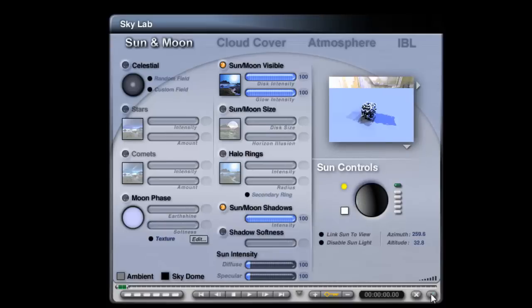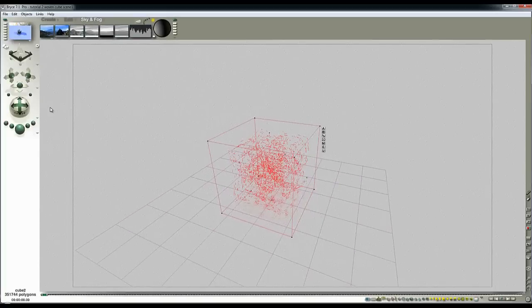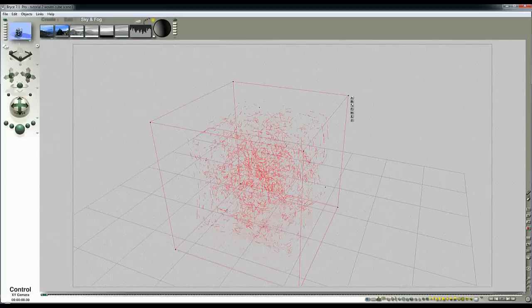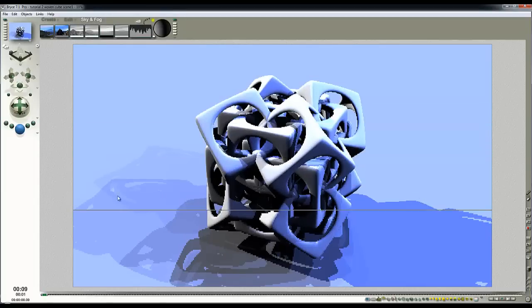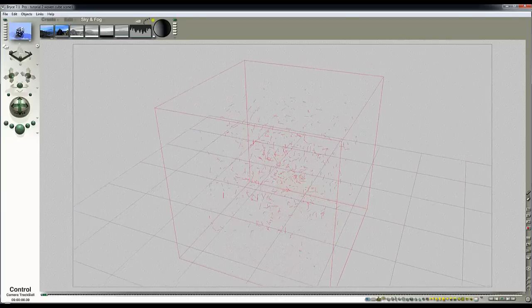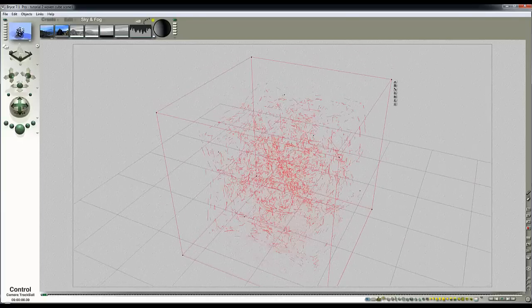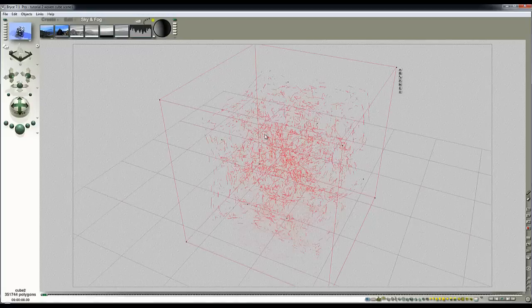Okay, right. Well, we'll use this as our opening gambit. I'm going to narrow the field of view to focus on the object in this scene and just give you an idea of the render time now. So it's only taking seconds to render, but as yet we've got no reflective materials in the scene, and the reflections do make a difference because it increases the amount of ray calculations that the render engine has to do.